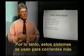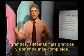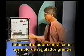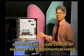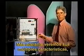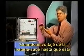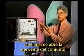These types of systems, therefore, are used for larger currents, larger systems, and perhaps more complex systems as well, because they're larger. An example of a large series type of regulator would be this central type of controller that's often used in telecommunication systems. A lot of features are built into this regulator. We'll review those later. But the basic charge regulation regime that's built in is that series type of control. When the battery voltage rises to a set point that indicates it's full, the array current is opened up.